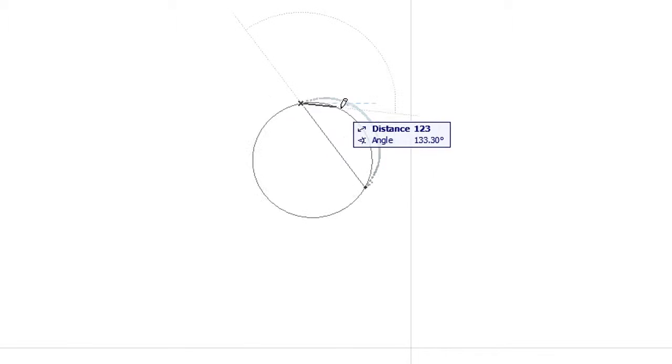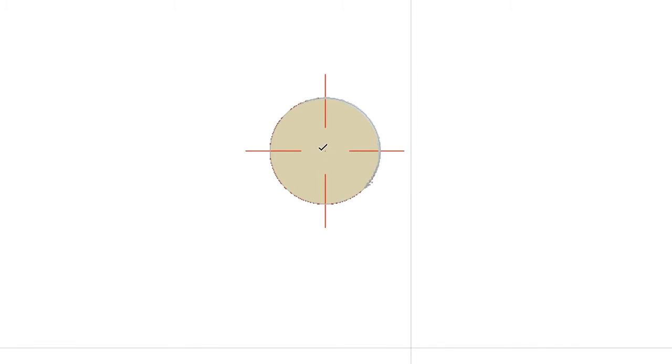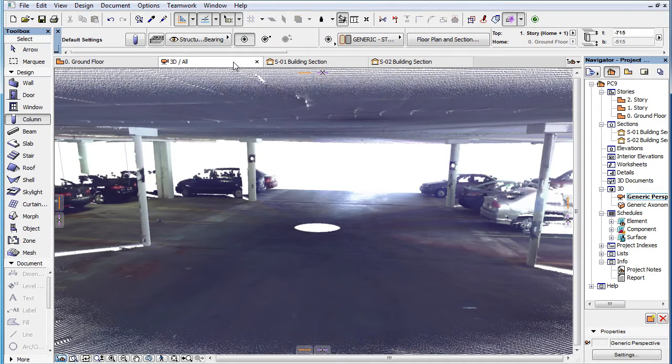The optimum thickness of this slice will depend on the resolution of the PointCloud data, meaning how close points that define the surfaces are located within the PointCloud object. Also, depending on your purpose, you may wish to see as few or as many points as possible.